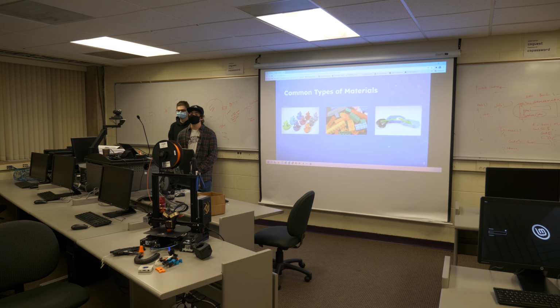It's very temperature resistant, requires quite a high printing temperature, around 260 degrees Celsius, so it's a very temperature resistant part, and it's again very durable and highly impact resistant, similar to ABS. However, the PETG tends to deform and move a little bit, whereas the ABS will eventually just shear rather than deforming with any of these impacts. However, again like ABS, it is very sensitive to UV light and will break down if you leave it outside for a long time.